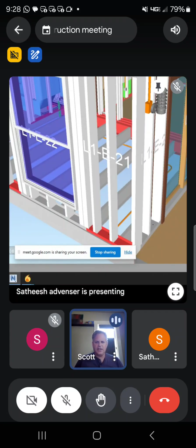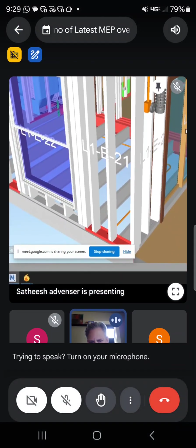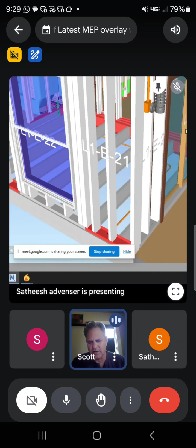Okay. Now, see the framing there, Sanjay? See the wall framing? Yep. Now, you see that the way they've done it is they have the wall framing coming right to there. And I think it's because you're going to pre-panelize this, right? Yes. And then this other wall is going to go on top of that, and then your floor joists are going to go on top of that. Yes. I think that needs to be thought out a little bit better.